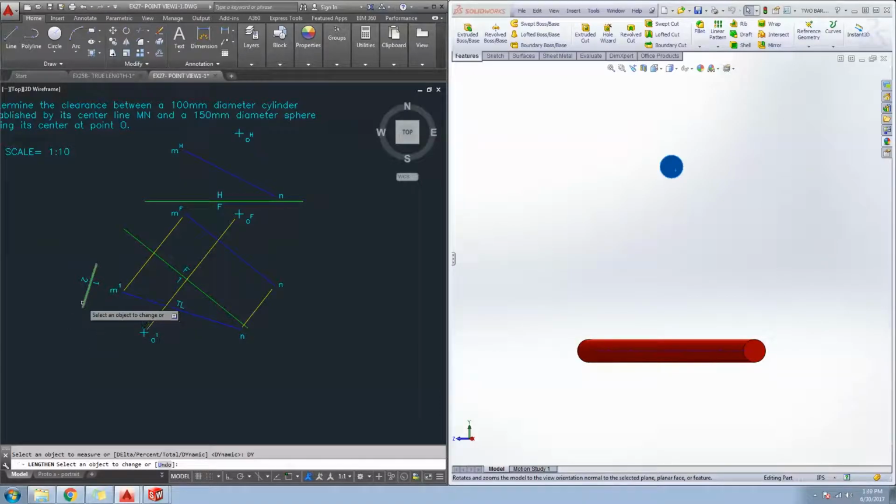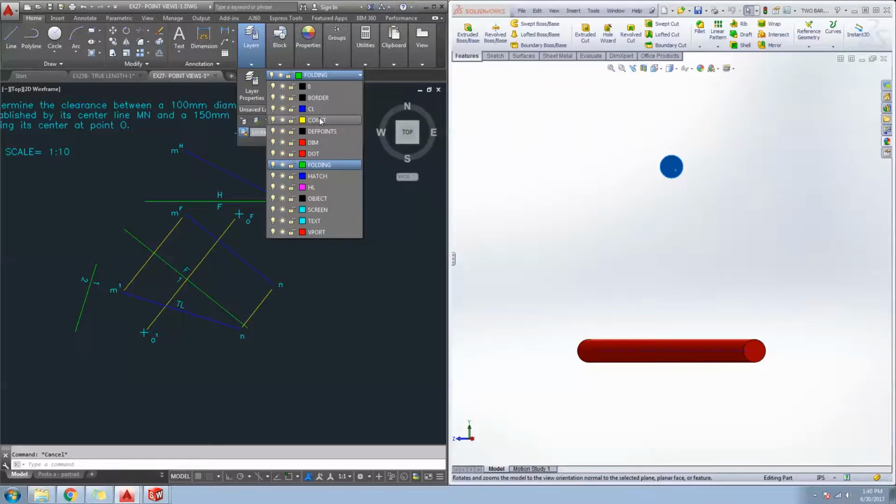I'm going to adjust the length of our folding line so it covers all the pieces, including O. It was too short there, and I can't draw a projection line if the folding line doesn't fully encapsulate everything that's here. Next step, we're going to move to the construction layer.